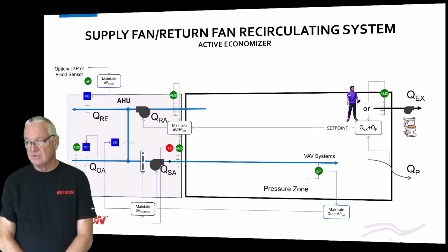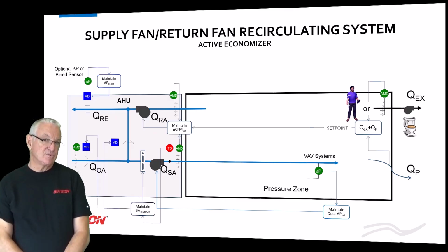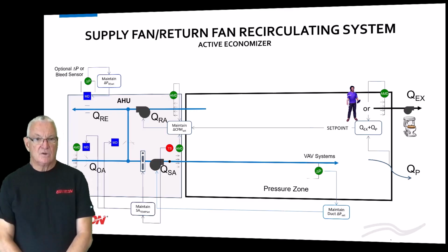If we get into a real cold climate, we have to watch that the outside air doesn't go below the minimum, and if it does, we have to switch into minimum outside air mode. Okay, so that's how that goes along.